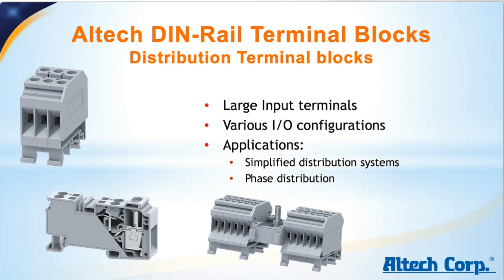Some of them have a larger input terminal, so high current inputs, and then smaller currents can be distributed to the outputs. These distribution terminal blocks are used, for example, for phase distribution systems, certain motor applications, and very simplified distribution systems within panels.